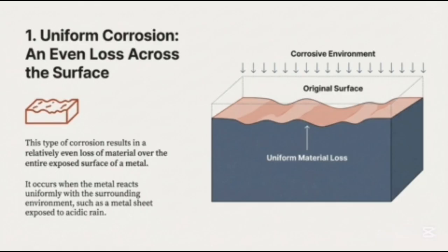It occurs in a uniform manner across the surface of the material. As can be seen in the following figure, corrosion occurs in all areas across the surface of the material. One of the most common causes of this type of corrosion is acid rain, because it affects all of the cross-sectional area of the surface.